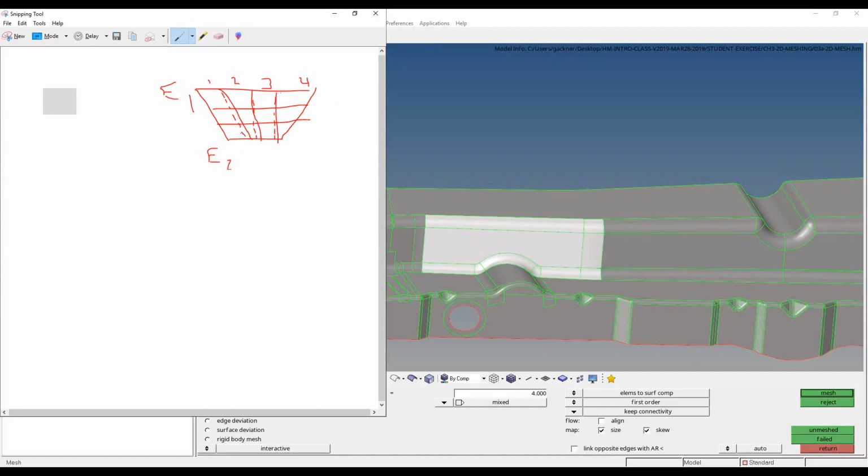But really what I've just done is model this with elements as small as 2 millimeters at the bottom, since this is only an 8 millimeter long edge. If the edge at the top is something as big as 80 millimeters, then what I've really just done is mesh something with 20 millimeter elements on the top of this little surface and then 2 millimeters on the bottom. Pardon the poor drawing.